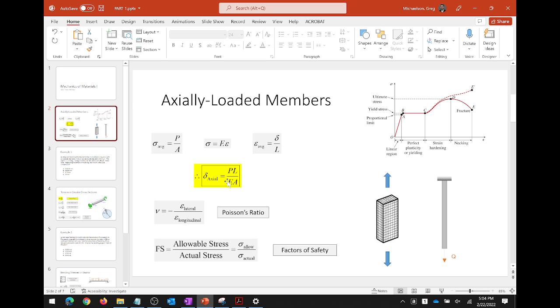All right, that's fine. So let me explain the meaning. That's a very good question. And let me explain the reasoning for the average term there. The reasoning for the average term there is what's called the St. Venant effect, or what I think would be easier for you to relate it to would be what happens in steel tension members under the presence of shear lag.